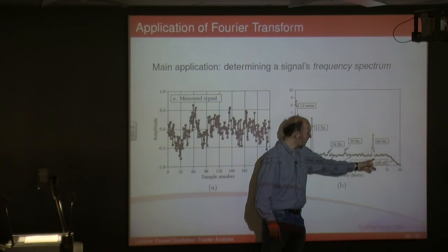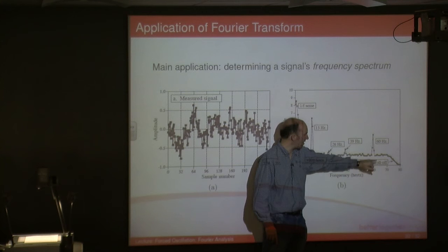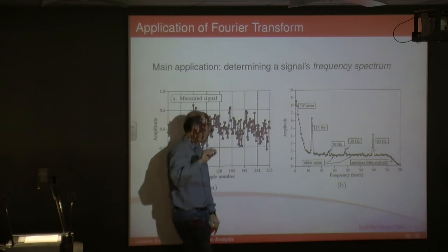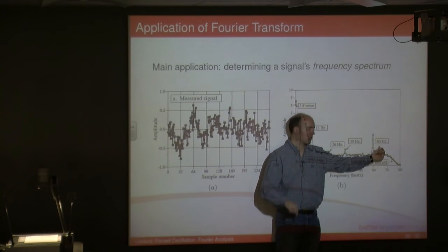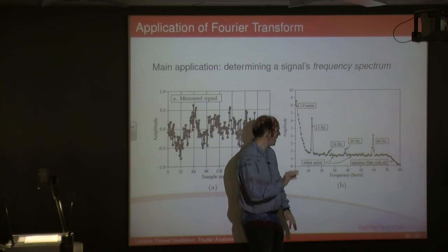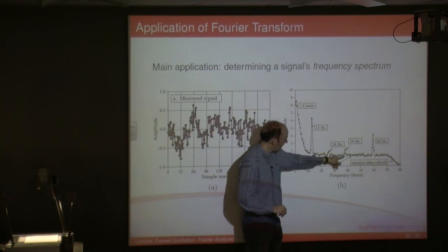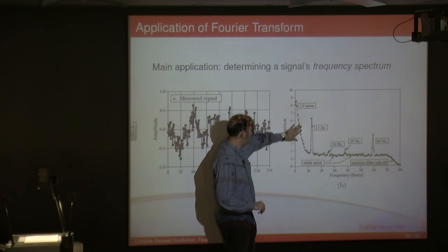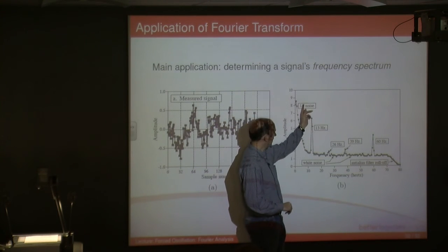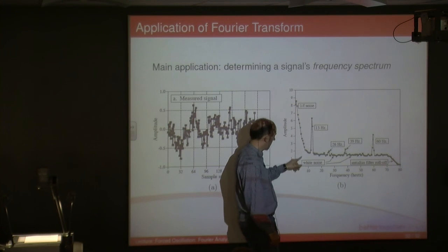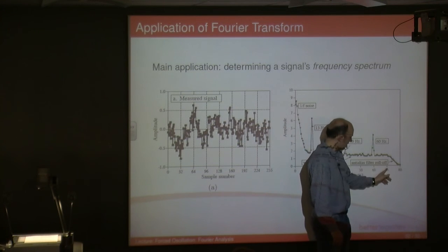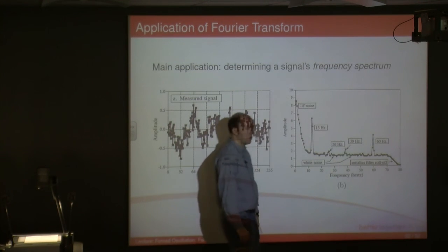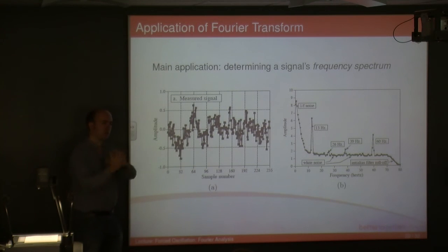This is probably because the thing was plugged into the mains in the United States, because the AC current in the United States oscillates at 60 hertz. I say the US because in this country it's 50 hertz, but there it's 60 hertz, so there's a peak there. And you've got this sort of background noise, which is simply white noise, called 1/f noise. What we've done is a bit of frequency conditioning, a bit of filtering, because we've knocked off any frequencies above 70 hertz. We've used what's known as a low-pass filter to just look at the lower frequencies and ignore the higher ones.